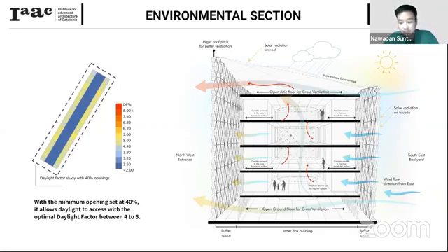And on the right side, the section shows how the wind ventilates through the building from the southeast to the northwest. The roof is lifted up on the west side for better flow according to the wind direction. And also the building core will provide the porosity for hot air to transfer up to the roof space before ventilating out of the building.